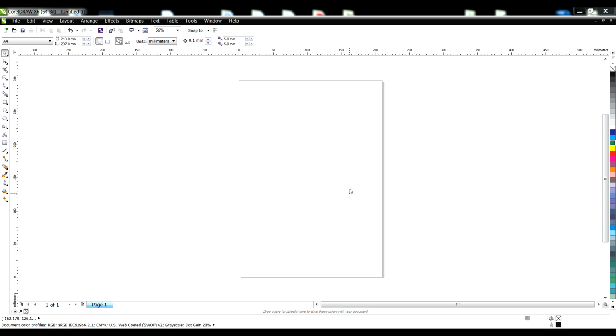Hi, this tutorial is for the star tool. The star tool is in our left tool palette, but we can't see it at this moment because it's in the same place as the polygon tool. We go to the polygon tool, press and hold our left mouse key on this black triangle, and as you can see, the star tool is the second tool of this palette.